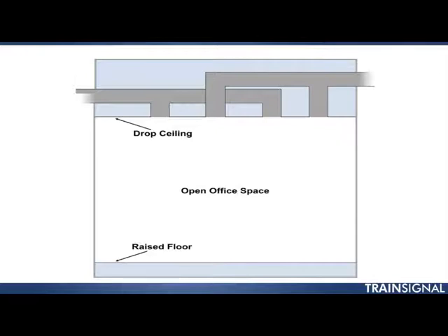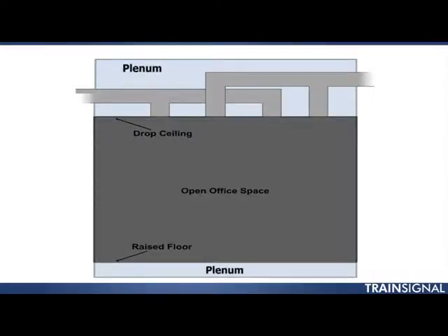If you are going to run cables in these hidden areas, especially if it's an area where air can gather, and even more so if that air can then be taken from that space and thrust into another space, especially an actual open space where people are breathing, it is important that you use what's called plenum grade cable. And the reason you want to use plenum grade cable when working in the plenum, which, by the way, is these hidden areas, that's the plenum.